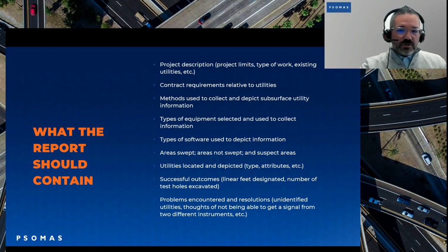Did you use a Sensors and Software's LMX 100? Did you use a Leica? What piece of equipment did you use and what accuracy? What method did you use when collecting it? So that when the engineer goes to depict those utilities, he has a better understanding of what you did, how you used it, and they can be able to assign risk. The type of equipment selected to use the information, also types of software used to depict the information.